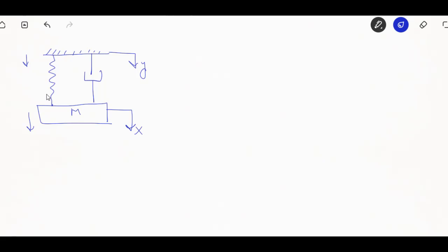Now when this situation arises, suppose a measuring instrument has been put over a system which is already in vibration motion, and by putting this particular instrument to gauge the vibration within the system, you will see that the system vibration translates into this instrument, and this instrument also has moved entirely. So when the system moves, we need to find the relative motion of this mass and this support as well, to ascertain the actual value of the vibration amplitude, right?